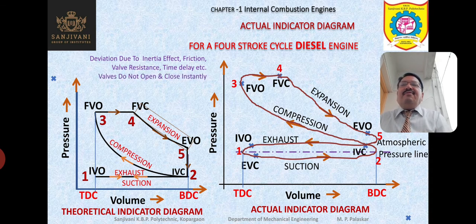So I told you that valves will not open or close instantly, and therefore the corners are rounded. The corners of the actual indicator diagram are rounded. One more important thing is about the pumping loss.